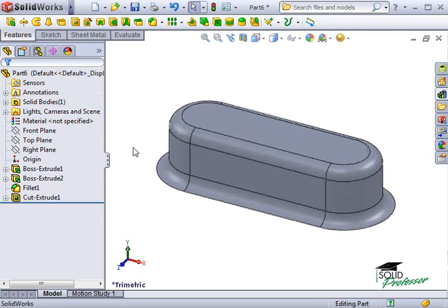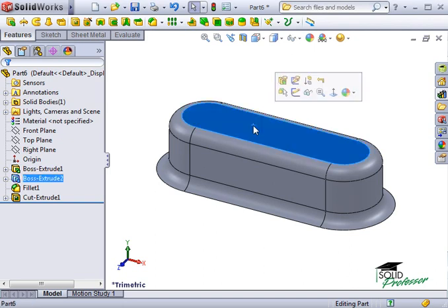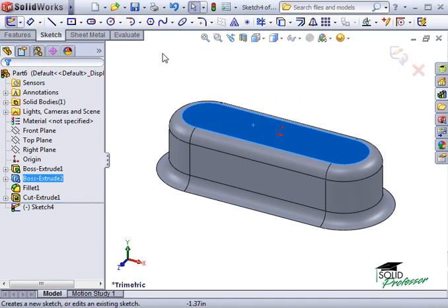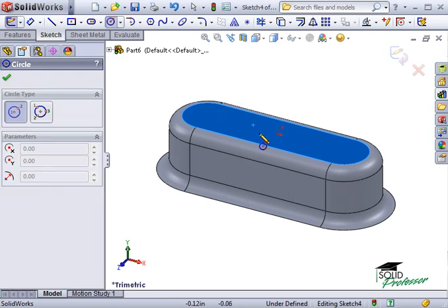In addition to stamping the shape into the sheet metal part, I also want this forming tool to create a round hole. In order to do this, I have to color a round face red. Unfortunately, I don't have a round face to color, so I'll have to create it. To create the round face, I'll have to use the split line feature. I'll start a sketch and create the shape I need, a simple circle.